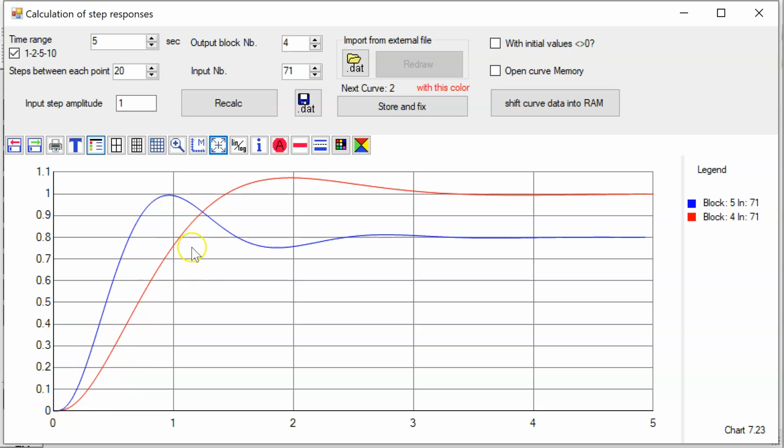So in this case, you see, this is a PI controller with a maximum point here at 1 second, slower than P. The omega d value is smaller, so we are not so fast, but the final value is exactly correct. This is the decision. If you go with the PI controller, forget the pure I controller. In this case, it plays no role in this situation.